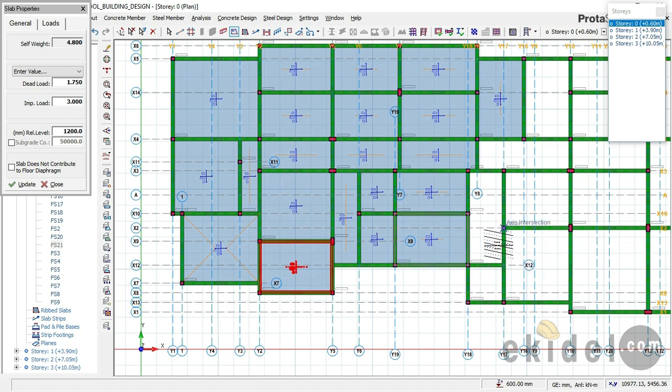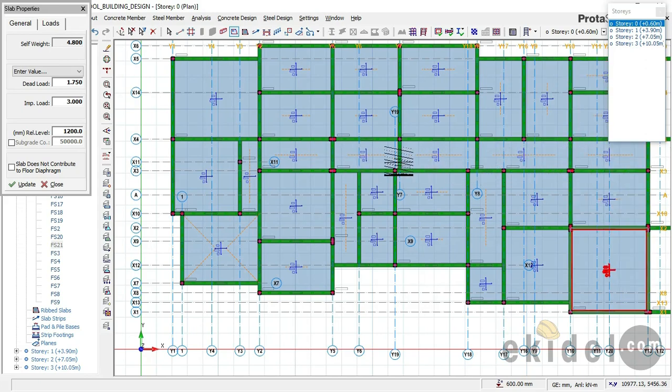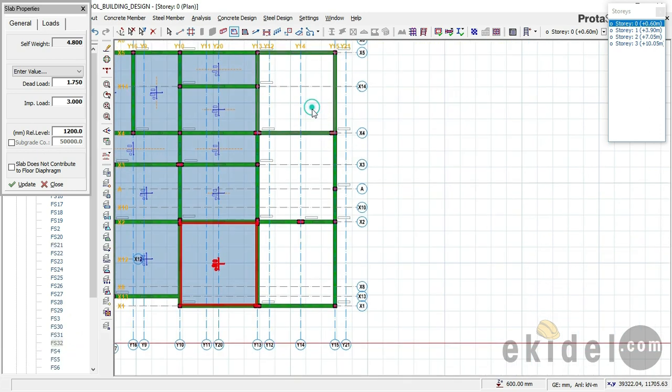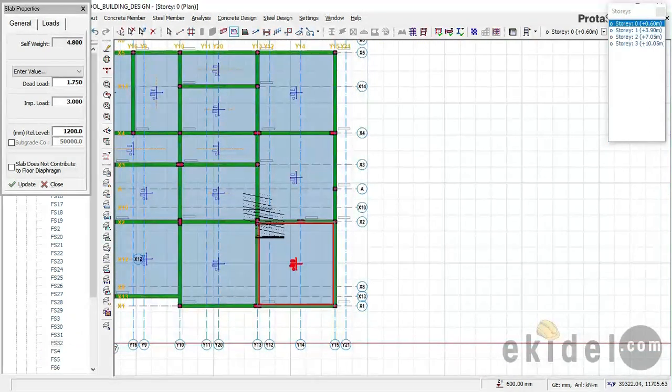Okay, so I'll just begin to insert my slabs, just confirming that I still have my level here. Okay, that's fine. So I begin to insert my slabs just now. Everywhere must have a slab on a raft foundation. So I begin to input my slabs just there right now. I'll just pan right now to see everywhere and then begin to put my slabs here. Okay, that's fine. So I'll now click on escape here.